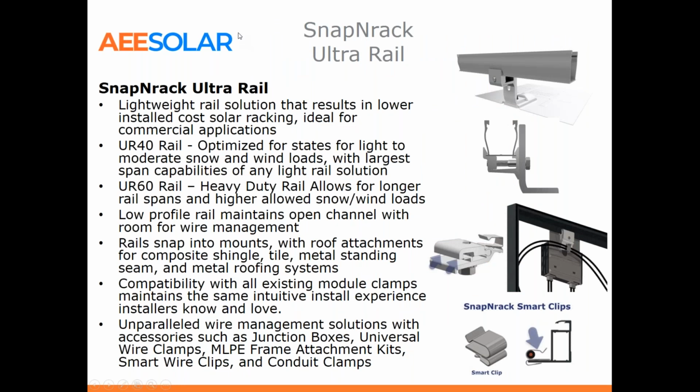Mentioned SnapNrack here, Ultra Rail. I'm going to fly through this. Most people should be fairly familiar with SnapNrack, but good for pitched roof systems attached to composition roofs, metal roofs, especially with their seam clamps and their metal roof bases. And we can mitigate for high wind and snow conditions if needed with the UR60 rail.